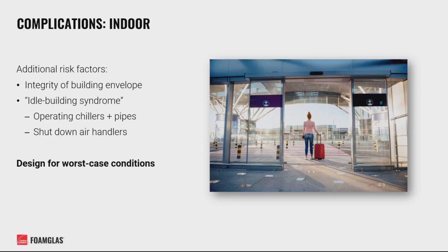This combination of unconditioned ambient air, along with the same cold chilled pipe surface, can create a prime environment for condensation to take place. In any scenario, you'll want to consider your specific environment and always design around the worst case conditions expected for your system.